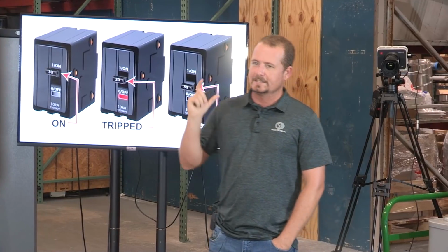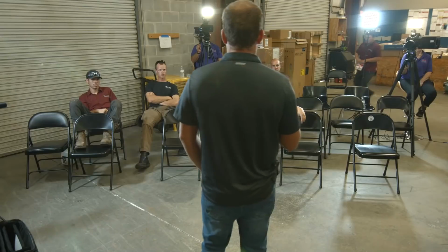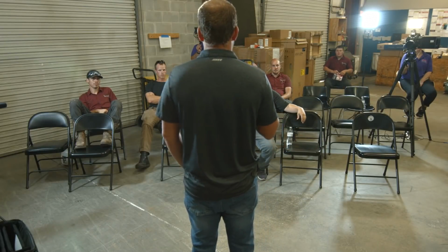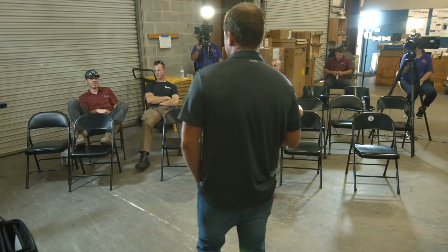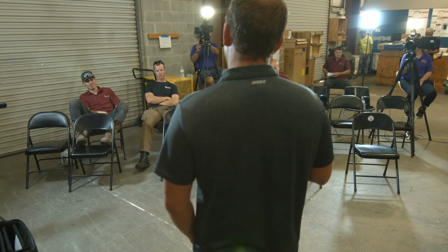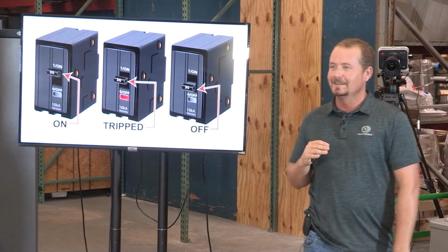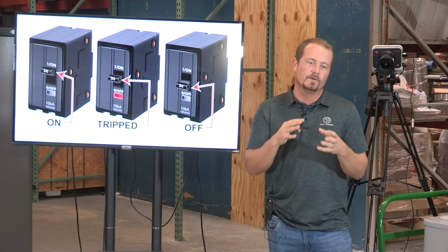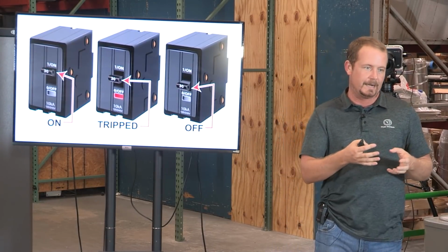Under what circumstances does a breaker trip? What causes a breaker to trip? Short. A short is what, again? Whenever the intended path takes an undesirable course that shortens the length of it. Okay, you said a lot of extra words there, but you kind of got to the point. A lot of fancy talking there. Yeah, so it's whenever there's a path of lower resistance than the design.